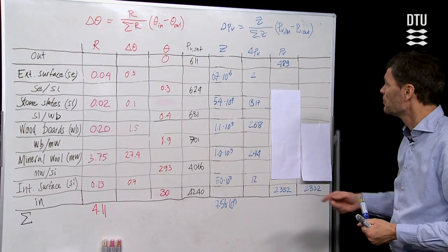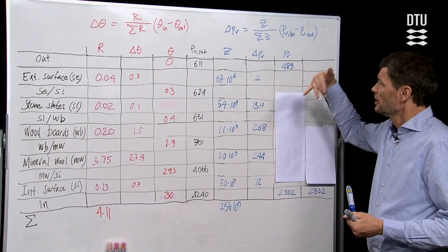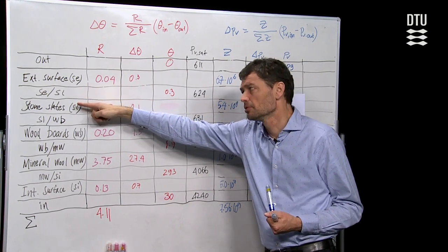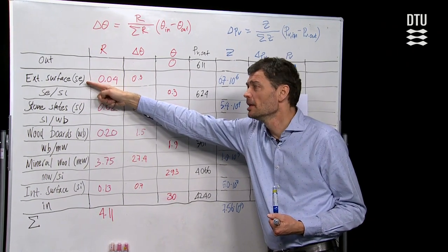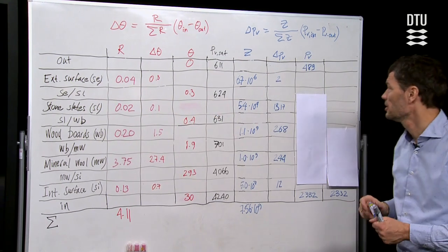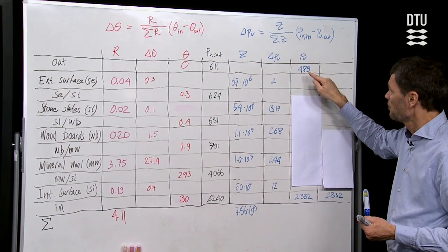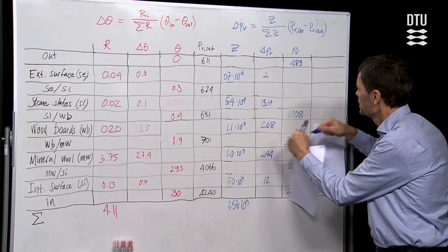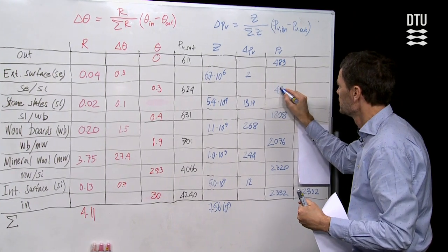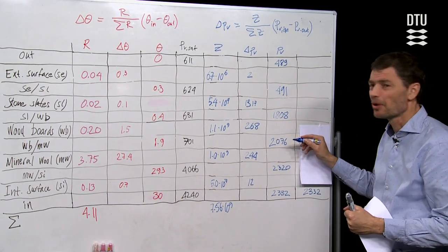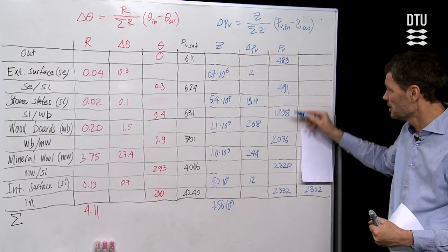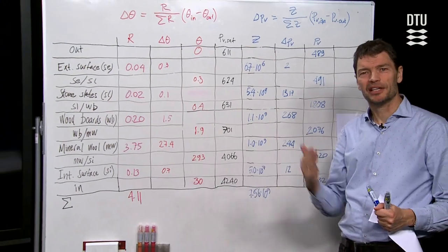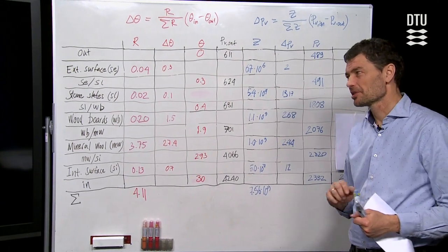Now the recipe is the same. We can calculate the vapor pressure at the interfaces, for instance at the exterior surface of the roof, the interface between the exterior surface resistance and the slates as a roof cover. Then it's 489 plus 2, so there we should have 491. As you can see, I have calculated and put on the whiteboard the results for all the other layers. So that's good, and we should think that we are done and can put those results on our results sheet.